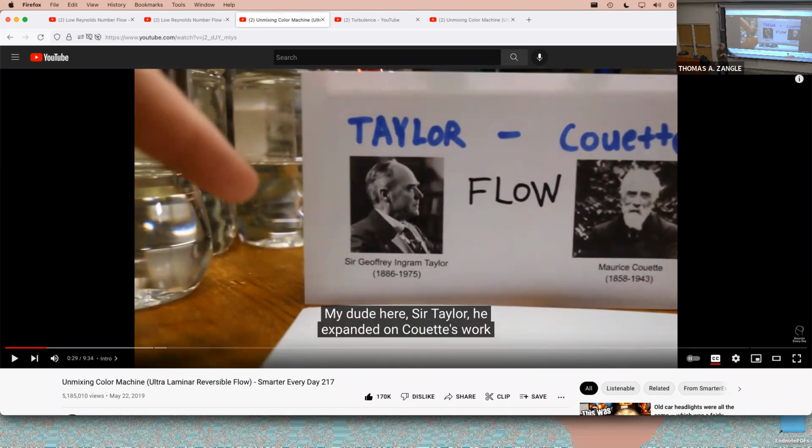Yeah, so this is a different type of viscometer. Essentially this device that we've seen is a rotation of the inner cylinder inside the outer cylinder. That's another type of viscometer, a way to measure the viscosity of a fluid. In this case, if we measure the force required to spin that inner cylinder, you can figure out what the viscosity of the fluid was.